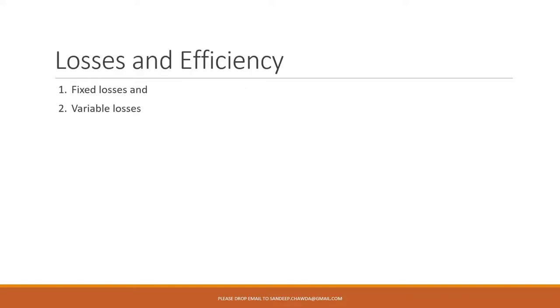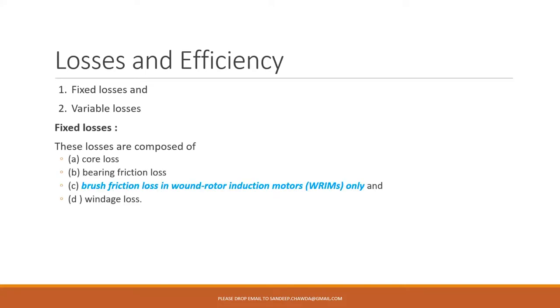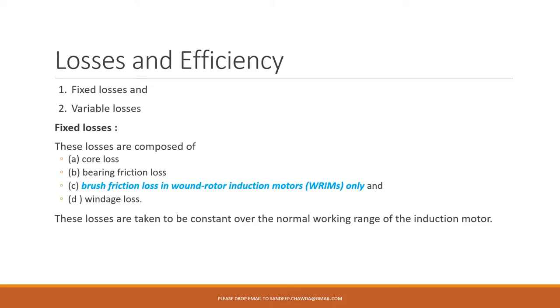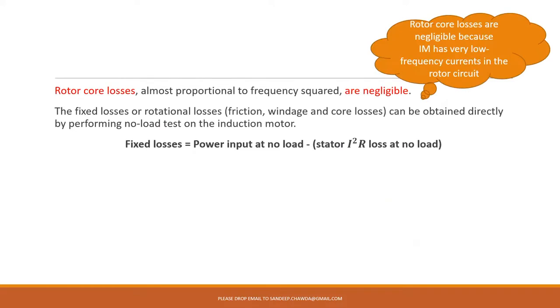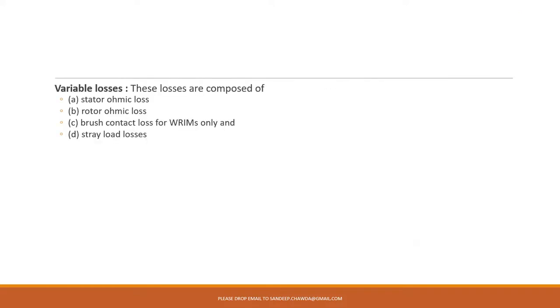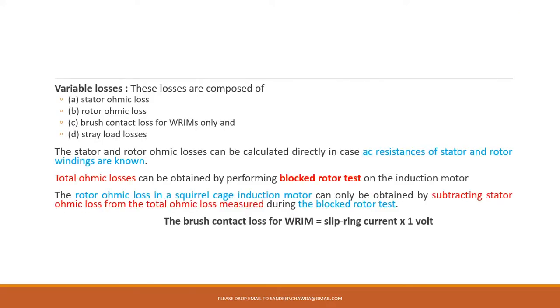Then we talked about losses, under which fixed and variable losses were discussed. How can we calculate the variable losses? Variable losses can be calculated using the blocked rotor test.